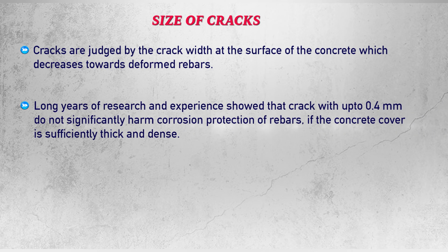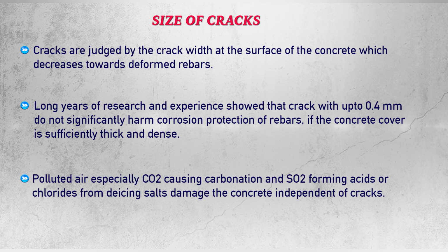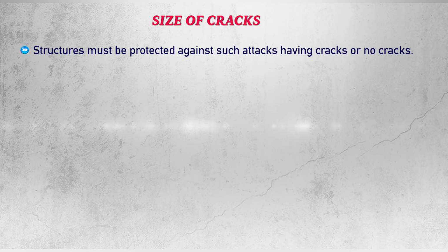Long years of research and experience showed that crack width up to 0.4 mm does not significantly harm corrosion protection of reinforcing bars if the concrete cover is sufficiently thick and dense. Polluted air, especially carbon dioxide, causing carbonation, and sulfur dioxide forming acids or chlorides from de-icing salts damage the concrete independent of cracks. Structures must be protected against such attacks having cracks or no cracks.